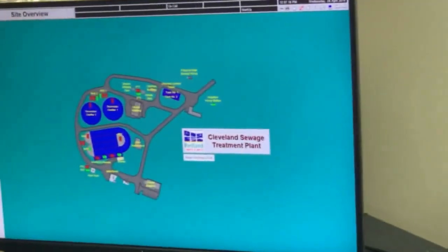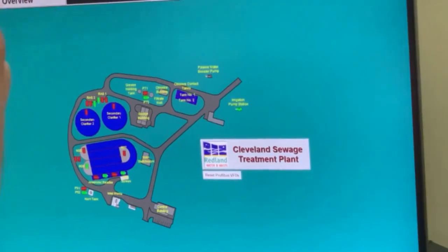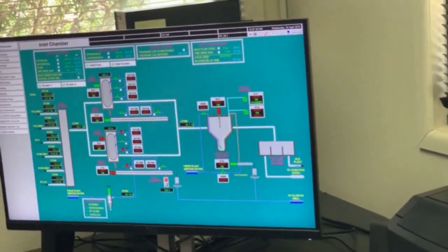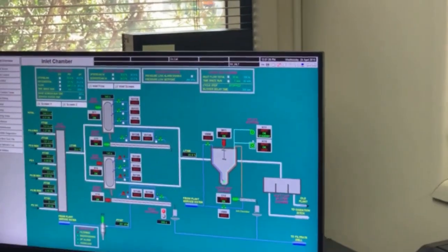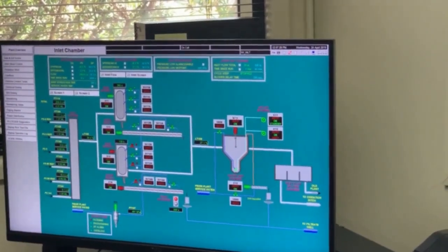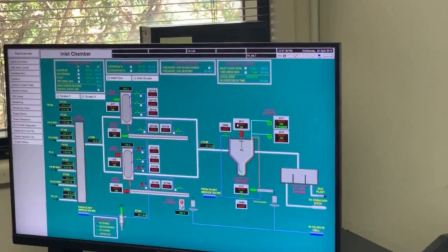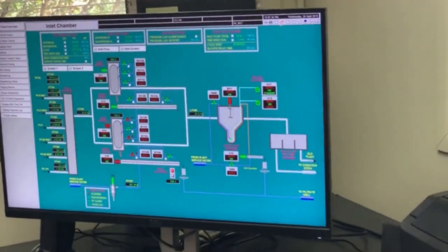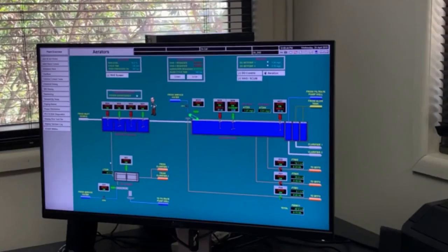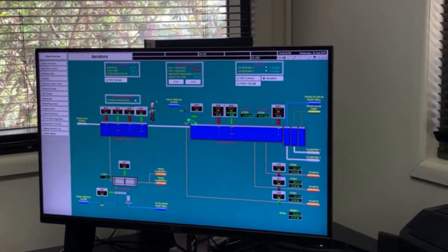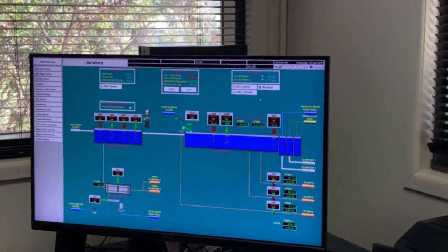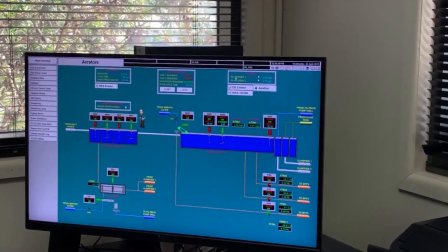The sewage treatment plant is managed by a control system which uses a SCADA program to control the working of the plant. The plant is thoroughly monitored by this software, and any warning or any change in the running process is notified instantaneously. It can be used to adjust the chlorine concentration, the amount of effluent present, and the dissolved oxygen level.